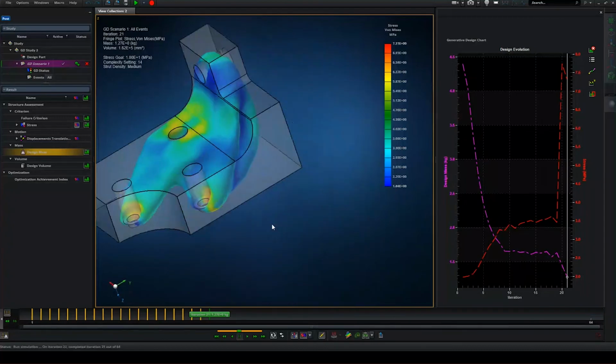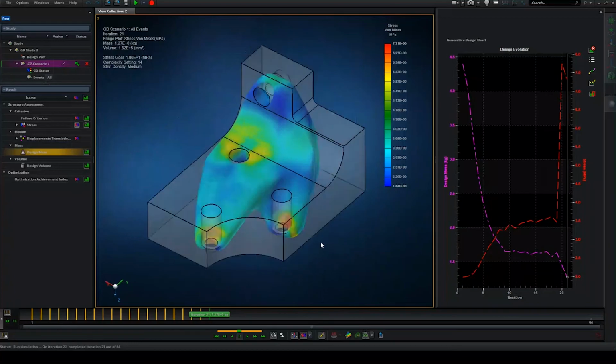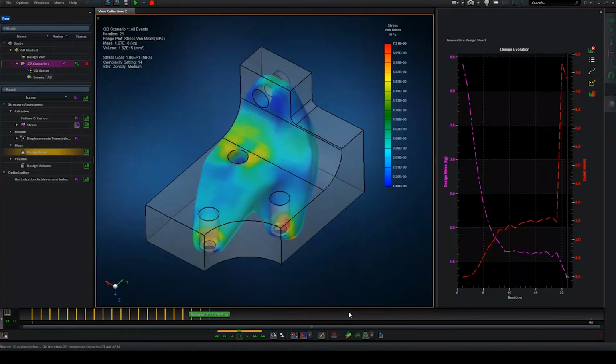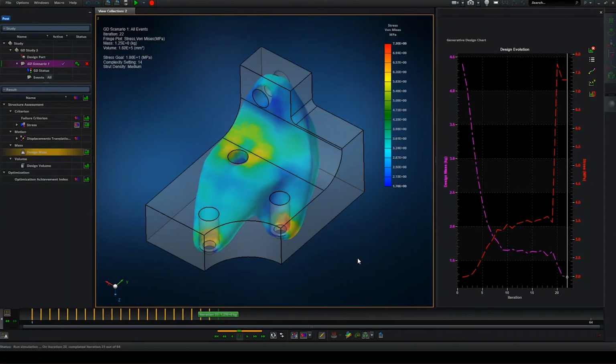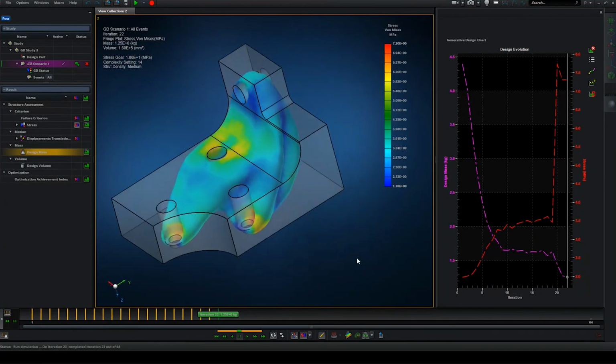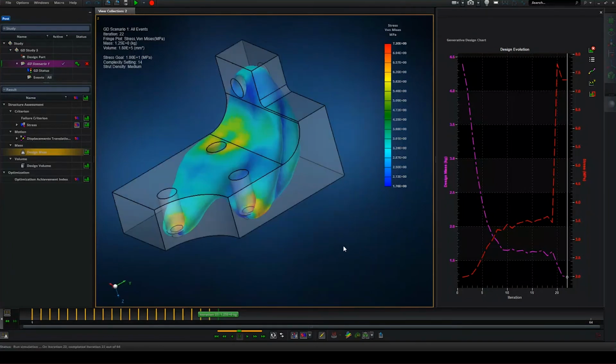And you will see cases like that further on as well, each time the internal mesh generator reduces cell size and increases the resolution of the result. So sometimes at that jump, the initial value may look very blocky, but then it resolves itself quite soon.